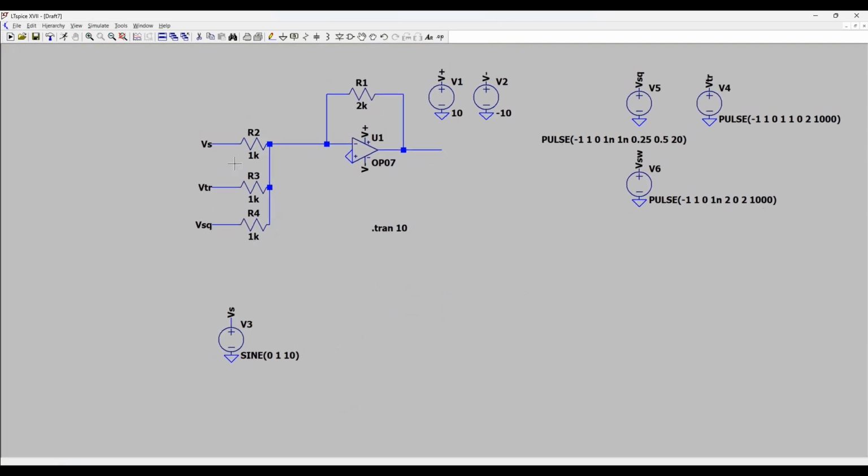And this is good for an example. In this case, let's assume our sine wave is actually coming from an analog source that's external, and we want to filter it to minimize some of that noise. So I'm just going to go ahead and get started by placing down some RC components, because I'm going to be making a notch filter, and the components that you're going to see me use in this schematic are catered towards creating a 60 hertz notch filter, because let's assume that we want to filter out some power line frequencies at 60 hertz. And I'm going to be eliminating this VS symbol because I'm going to be attaching it to the end.